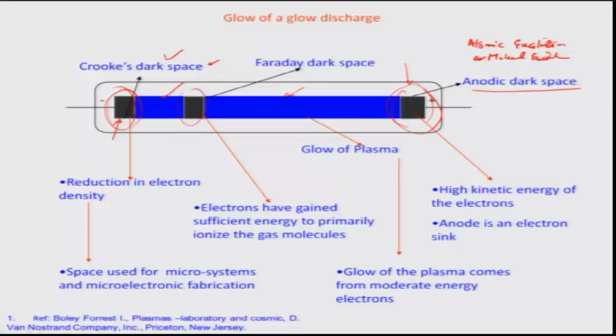And so, therefore, you have a dark space here, the anodic dark space, and in between there is obviously an area where the momentum of the electrons which are going to create additional secondaries are such that they would knock off the electrons from the atomic species rather than mildly or moderately excite them. So, there is a region where this knocking off tendency would happen, where the electron energy is completely absorbed, beyond which the electron again starts to go by, and so therefore, there is a space which is completely filled with ionized species again in between the two cathodes and anodes,